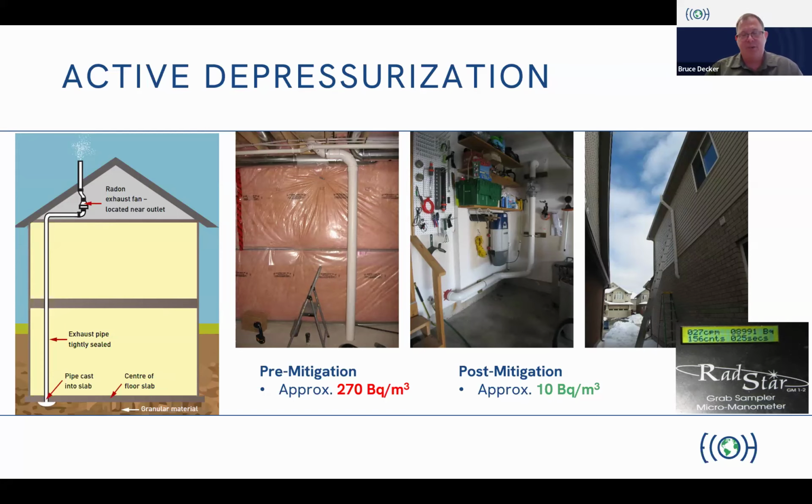We did a grab sample underneath my floor before we started this. And you can see here that the radon pinned at close to 9,000 becquerels under the slab. After we put the system in, we let it run for a day or a few days. Those levels underground dropped to about 400. So that's a washout effect. And if by chance the radon slurps in under certain circumstances, it's coming in at far less concentration, so far safer.